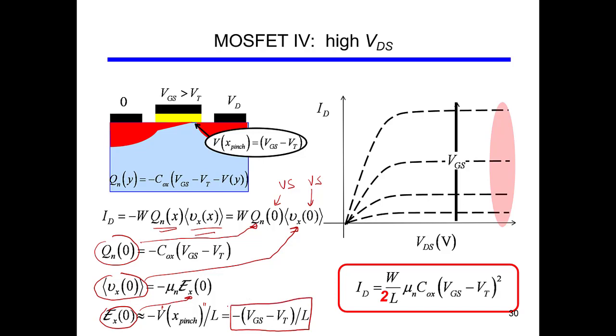So we put all these into the equation and we get this equation, which is the equation of ID versus VDS in the saturation region. One thing is that in this equation we have this 2, but this 2 comes from some mathematical manipulation. Overall you see that ID is proportional to VGS minus VT whole square. So remember the square law model.